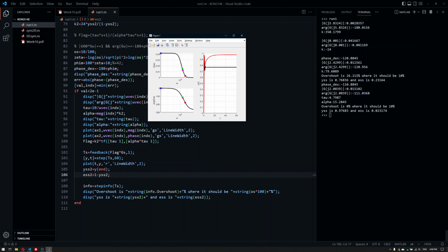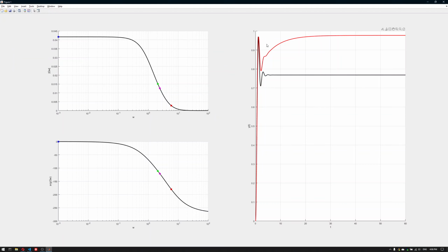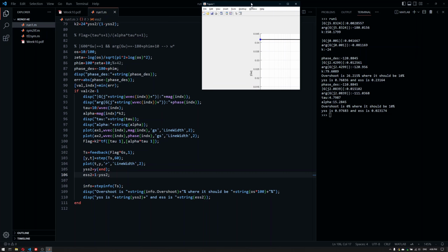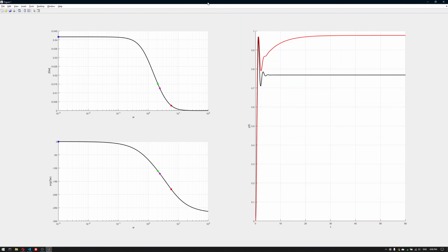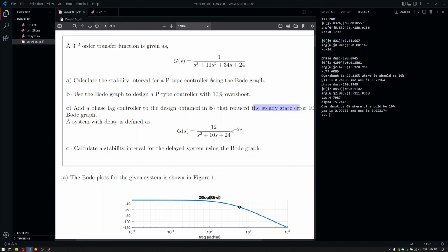We can see the overshoot is too much, of course, but adding a lag controller gets rid of that and you get a better result here where you can see the transients are even better, but it takes again a little bit time to reach that. It seems like we are forcing it, and this is the best that we can get out of the system because the system is already slow and we try to apply a high gain, even though when we use just a single KP or the P-type controller, this was not even possible because it was not stable. The lag controller was able to stabilize it and force the system eventually to the point where we want it to be, but it seems like our specifications are a little bit off.